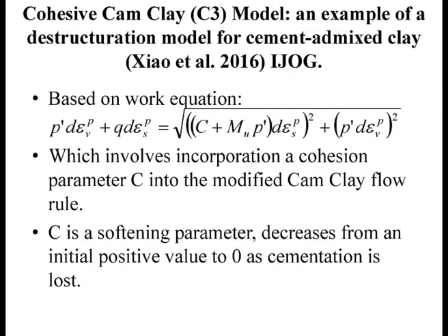It only applies to remolded soil. Remolded soil means you remold it, and so there cannot be a cohesion. It's completely remolded. That is the logic. That is the rationale of the Modified Cam Clay. That's why Modified Cam Clay never considers cohesion. Now you might say that there is a class of material which is heavily overconsolidated soil. Some people also measure cohesion, but the way the Modified Cam Clay would address this issue is this.